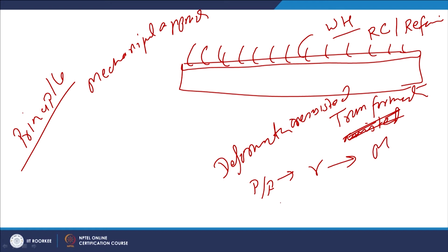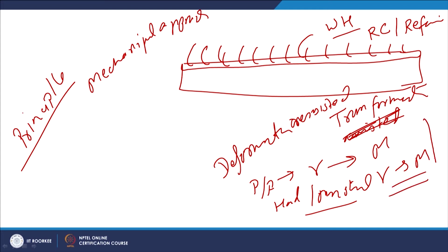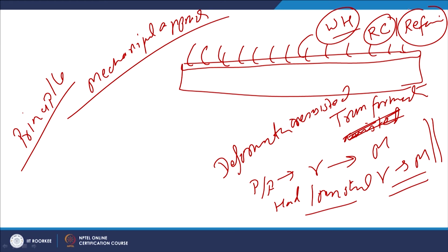And sometimes, like in Hadfield steel or high manganese steels, the austenite transforms into martensite. So, there can be deformation assisted transformation in some categories of steels. In the mechanical based approach, where localized plastic deformation is used to enhance the surface properties, work hardening, recrystallization, grain refinement, and sometimes even transformation hardening help to improve the properties.